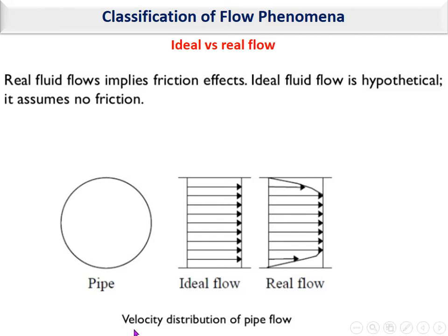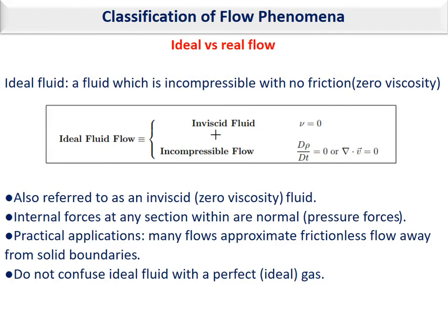Can we use it? In some special cases, by some approximation, you may use the ideal flow solution instead of real flow solution. What's the reason to solve for a flow which will not give you right results? Because of simplification. But please note to simplify the problem, not more than required.